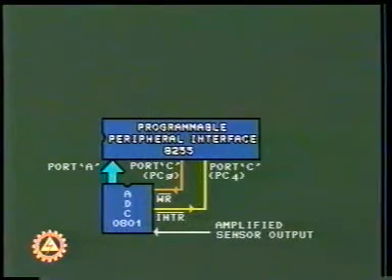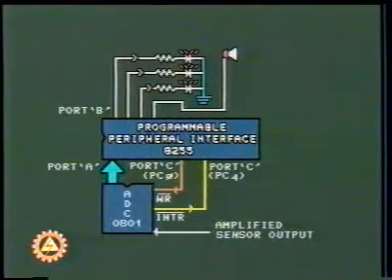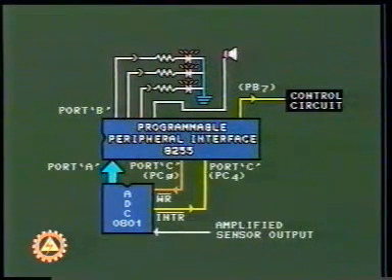The port B of 8255 is being used in output mode for generating the audio and visual indications regarding status of the system. However, the PB7 line is dedicated to fire the control circuit for pouring chemical into the process.